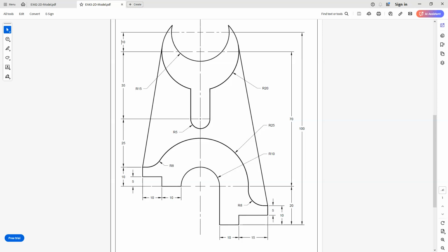Okay, so before we get started, some things that are really observant to me that I need to figure out is that these lines here, right? From here to here, you can see that the distance is not given, and if you're one of these advanced AutoCAD users or used to looking at drawings, you can spot this right off the bat and say, hey, I know the distance of that. For you first-time users looking at drawings, you can see that I have a radius of 5 here. So that's going to tell me that the distance from here to here is 5, and then going across is another 5. So that just simply says that this thickness here is a distance of 10, right?